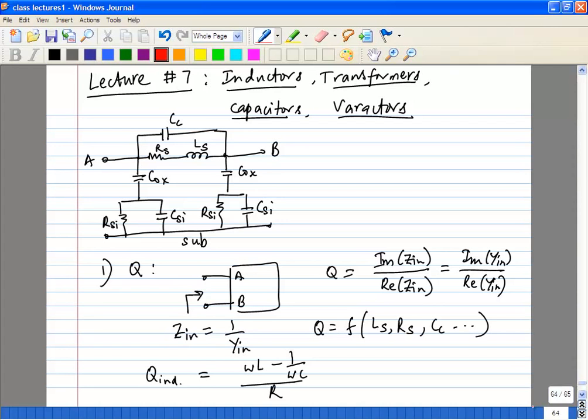But you'll be trading off: the underpass will be on an even lower metal layer, so that underpass may dominate your series resistance, for example. So there are lots of trade-offs depending on the type of inductor you choose to design. Yes.